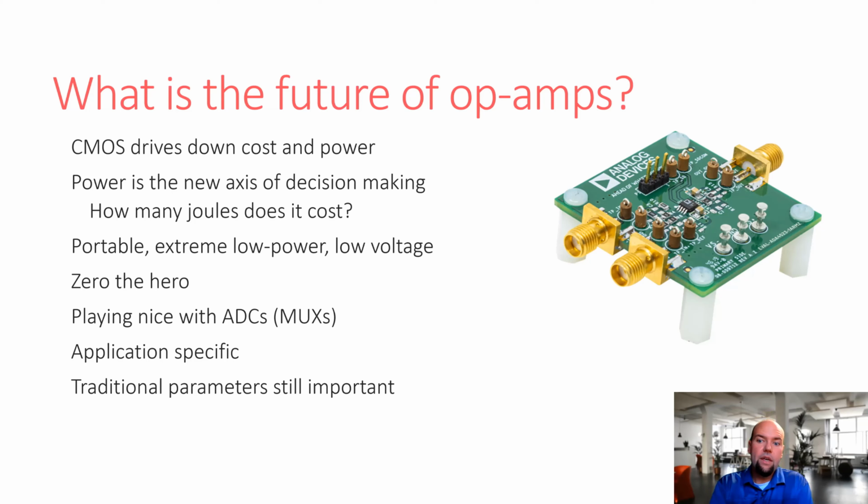And an op amp, you might build an op amp that's really good at 3 of those considerations and really bad at 2 of them. So for instance, it might be really good at high gain. It might be really good to have a high gain bandwidth product. It might be really low power, but it might have a pretty bad voltage offset, or it might have a pretty bad current offset.